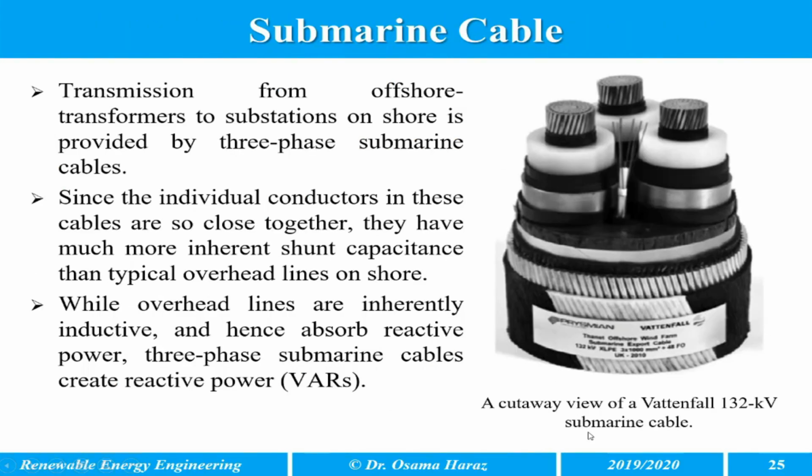This is an example of submarine cable, a cutaway view of a 132 kilovolt submarine cable. Transmission from the offshore transformer to substations onshore is provided by three-phase submarine cables. Since the individual conductors in these cables are so close together, they have much more inherent shunt capacitance than typical overhead lines onshore. While overhead lines are inherently inductive and hence absorb reactive power, three-phase submarine cable creates reactive power, VARs.